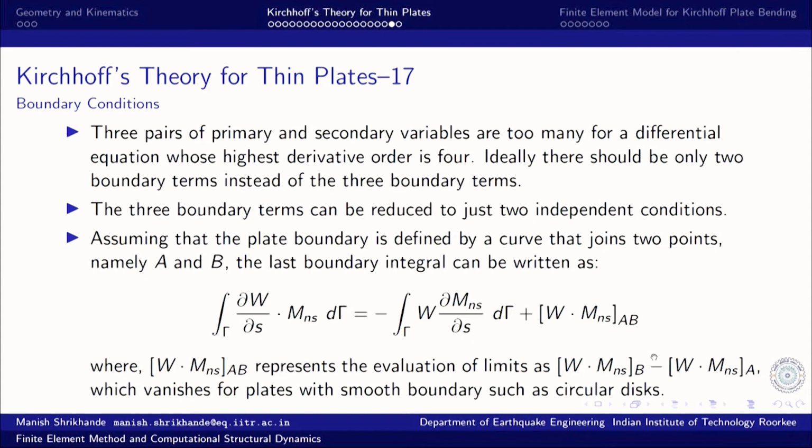But for plates with sharp corners, this will not in general cancel out, and that will lead to what we have as unbalanced shear force at the corners, and that will lead to lifting up of the corners.